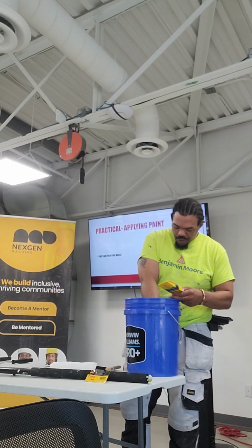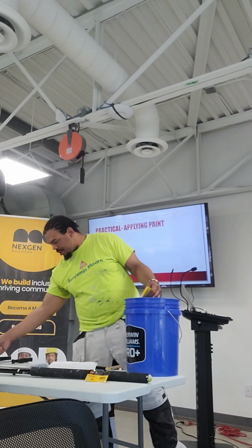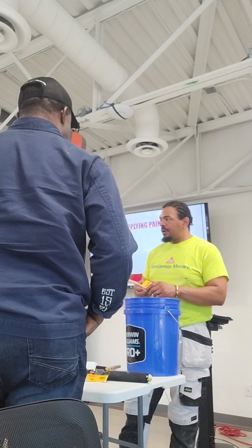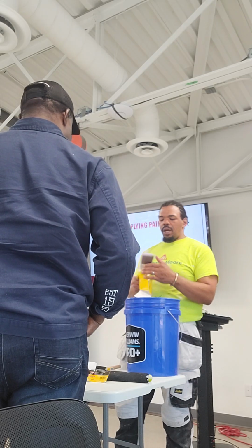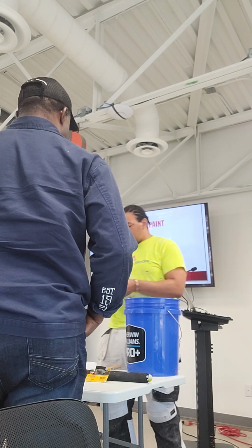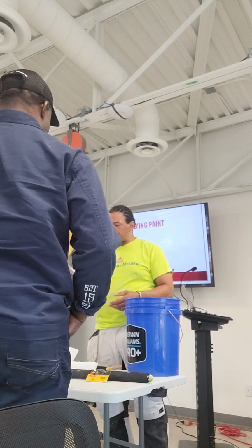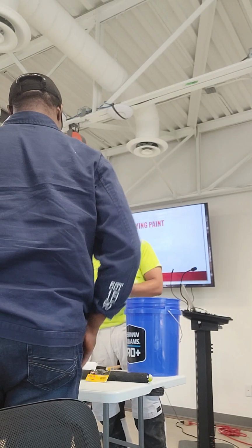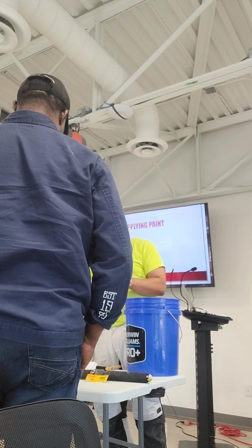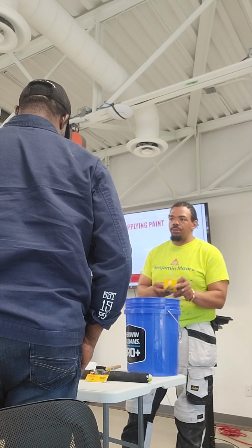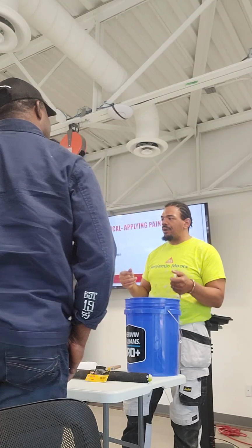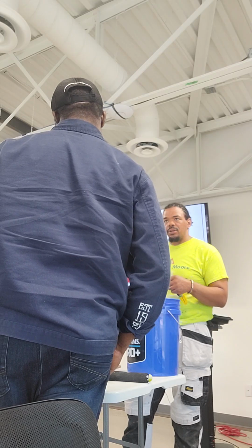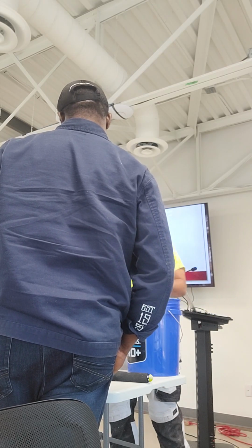So just to get you guys started, you have a mini roller. We won't need to use these today, we'll do the demo with one thing, okay? Now, the brushes that they donated for us today are Purdy soft bristle brushes. Very nice. I like to use these brushes on walls. They're a little stiffer than most other brushes. I prefer a stiffer brush on walls because wall paint tends to be a little thicker, a little bit more viscous, and you need better control of it. So a brush with a little bit more stiffness in the bristle, I think, goes further.